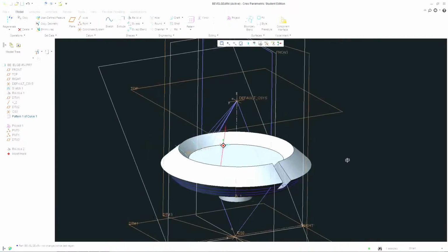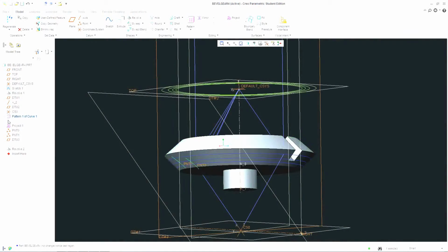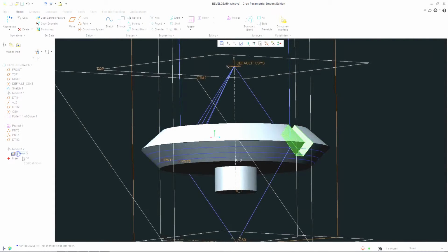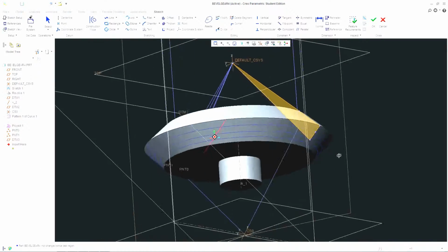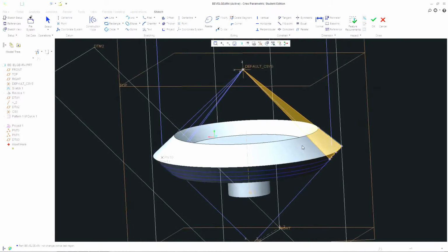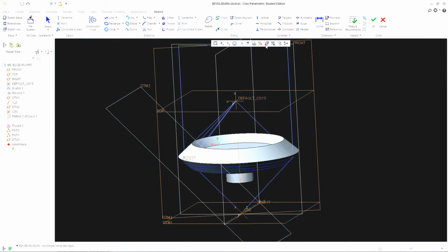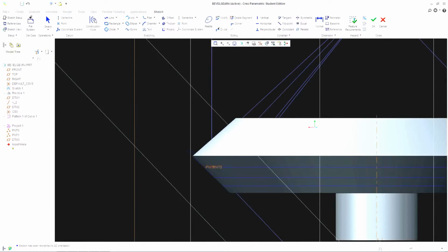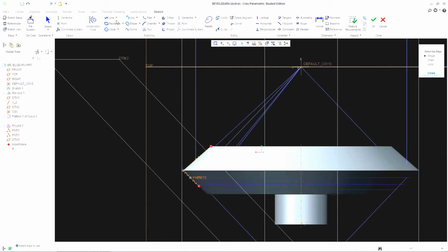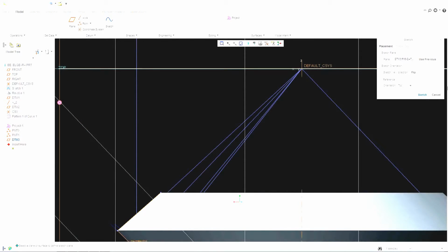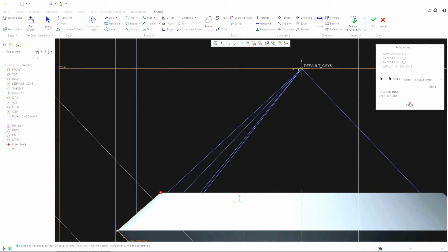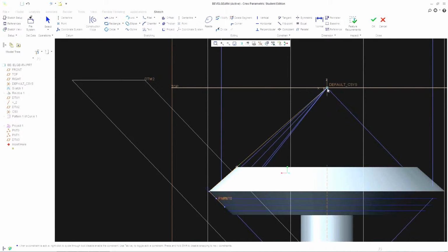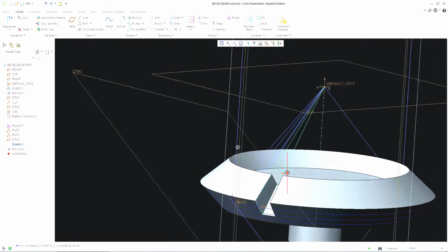Alright, looks like I did it on the wrong side. So there's a mistake there. Okay, so I should be drawing on this side because the plane flipped over. Just fix that up. Just draw the shape on this side. Okay, it's not connecting to the apex there. Click on reference. Bring that point out and close off that shape. And accept. And there you go, that's much better.